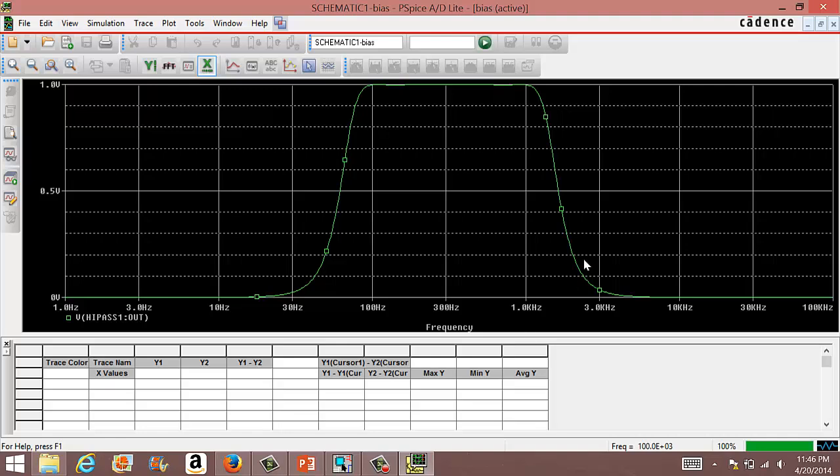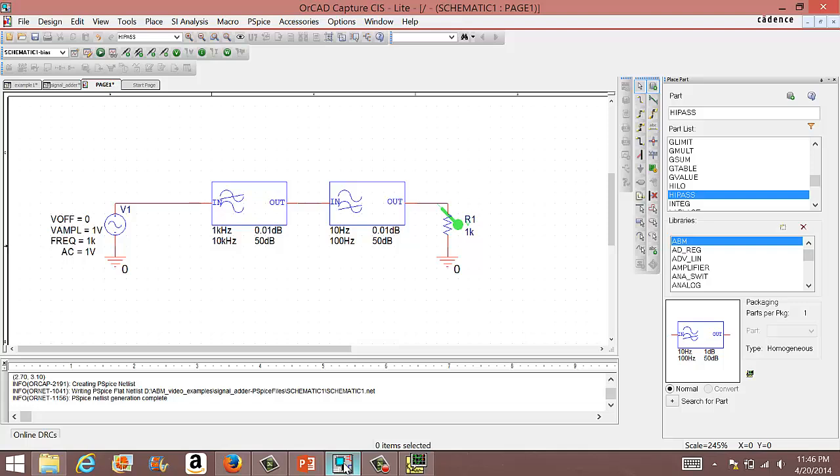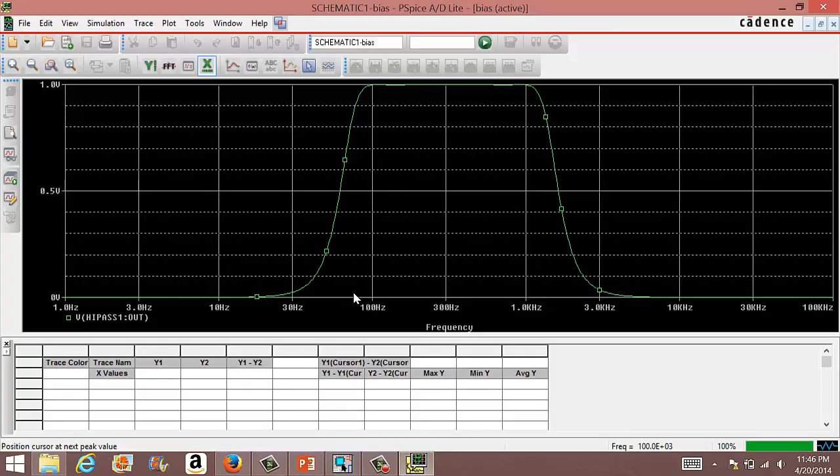All right, great. So we have right here a band pass filter. What I did is pretty much a low pass filter with a high pass filter, so it's just accepting from 100 hertz up to 1K. Okay, the bandwidth right there.